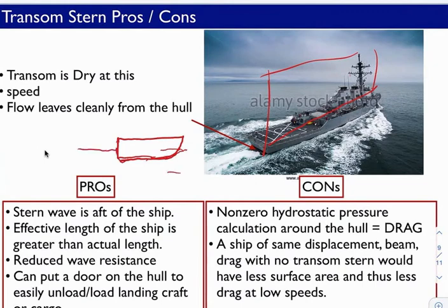Once you get to higher speeds, it will break away, because essentially it's a sharp edge here, and the fluid will leave cleanly from this transom. Cleanly's maybe not the best word, but it's breaking away from the transom here, leaving this gap. And you can see the entire transom, including what is normally wetted when it's sitting at the dock, is now completely exposed to the air.